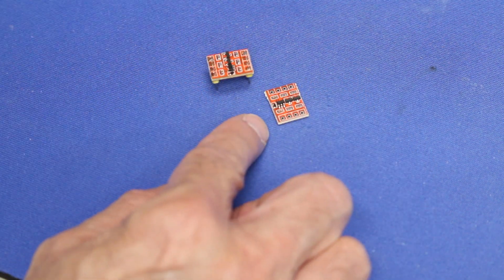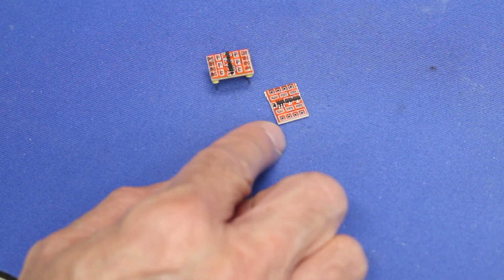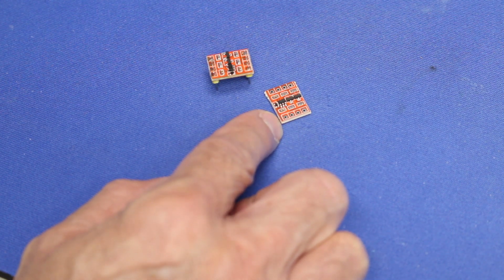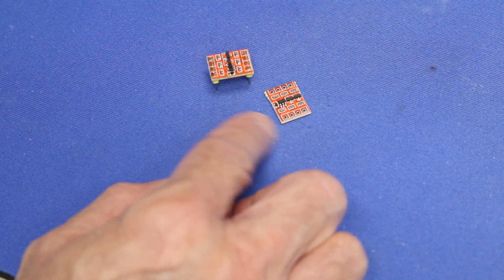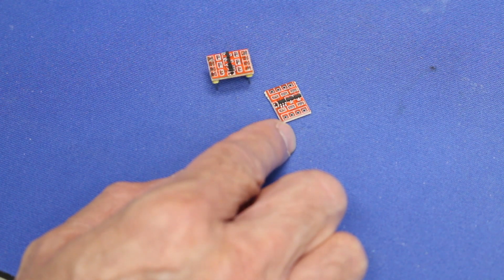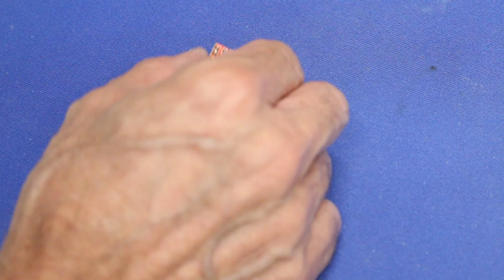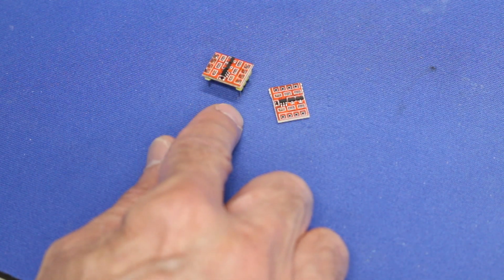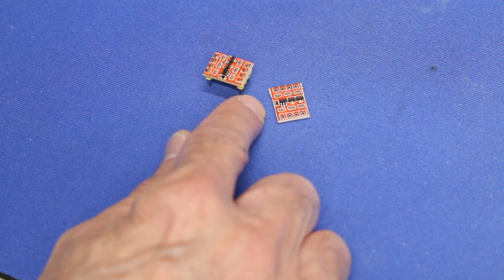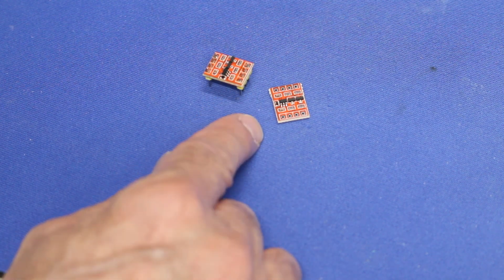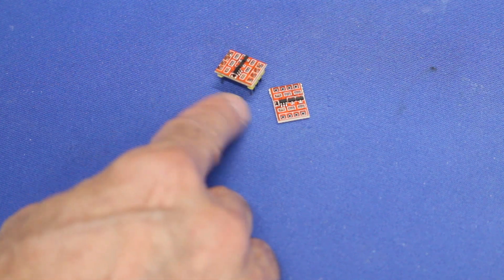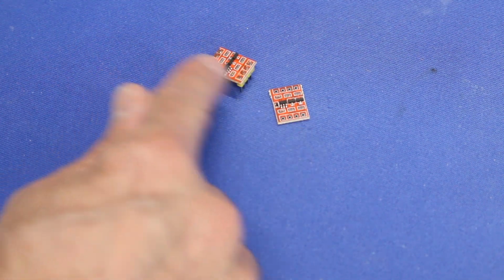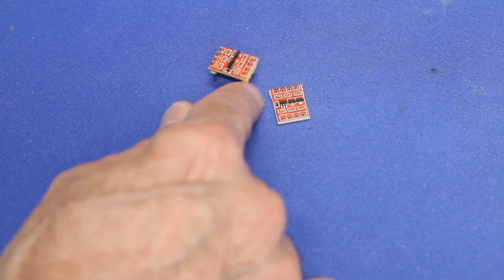Now, they're very, very inexpensive. You should be able to pick up a handful of these things for a couple of dollars. And for 3.3 volt to 5 volt logic applications, these things are great. Now, these are dual channel bidirectional converters. You can also get 4-channel and 8-channel ones if you wish. Just make certain when you are getting a converter, you are getting a bidirectional converter, a converter that can handle data going in either direction.